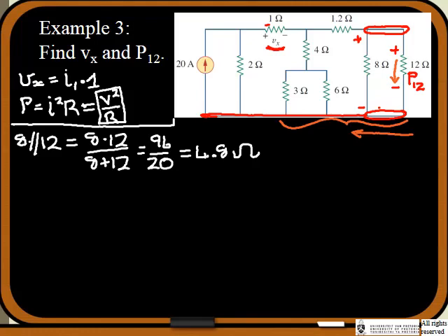So now we should actually redraw the circuit. When starting out with circuits like these, it's very important that every time you've simplified the circuit, you redraw it, and it will come in handy. You'll see it later on. So what does our new circuit look like? We've got a current source, then a resistor down here, then our 1 ohm resistor that we're actually after.